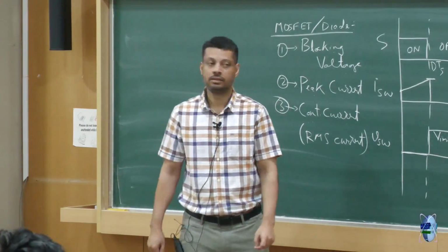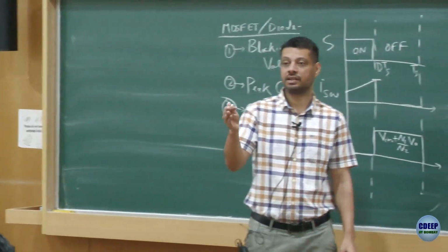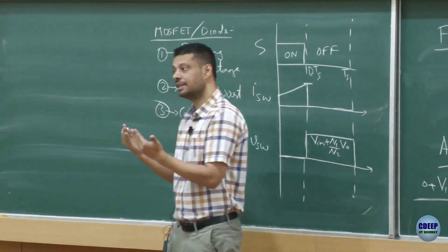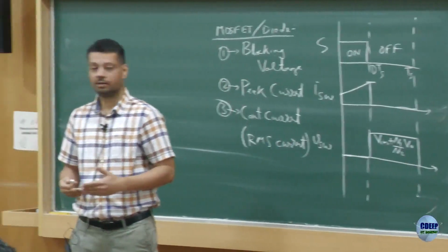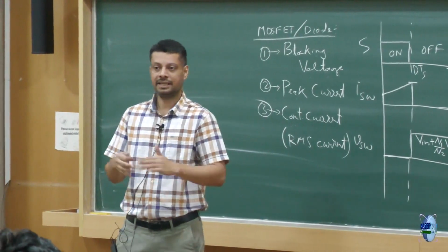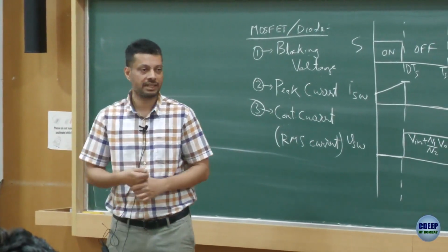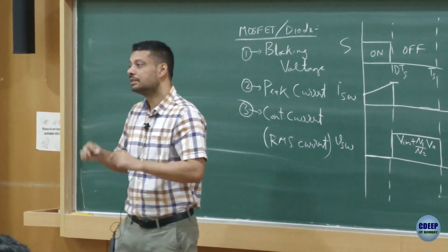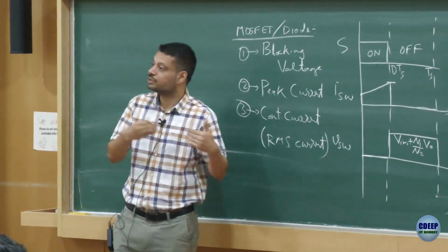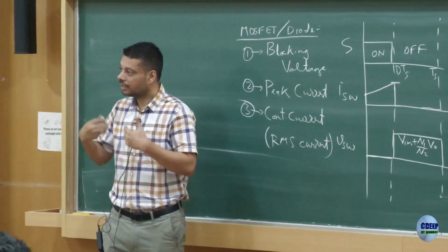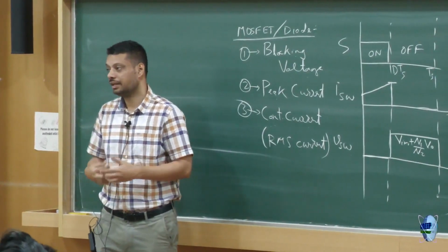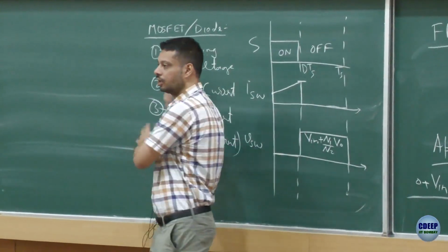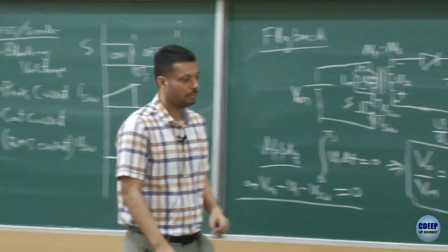Any question? Yeah, somebody said switching frequency, right? Of course switching frequency will matter, but if you open a device data sheet, have you seen a MOSFET data sheet? Once you go back, just Google any MOSFET, TI MOSFET, or any MOSFET data sheet. They will not specifically say this MOSFET is designed for this switching frequency. You have to decide which frequency you want to use the particular MOSFET for in your application. And how do you decide it? It is based on the losses, so that indirectly plays a role here. That is level 2, not level 1. Level 1 is these 3 basic things in deciding a MOSFET.